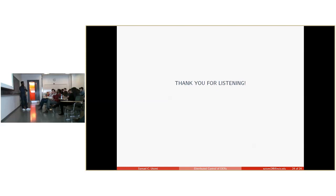All I can say is that we've worked on another paper where instead of distributing the resource based on their capacities, we distribute them to minimize the losses in the system. We have distribution lines with certain power losses, and thus at the microgrid to the bulk grid connection point, we have a certain amount of power that is less than expected. So instead, we optimize the amount of power that goes out to the bulk grid such that it matches the expected. In that situation, instead of having the capacities, it's more of an optimization problem where we determine Y and Z accordingly.